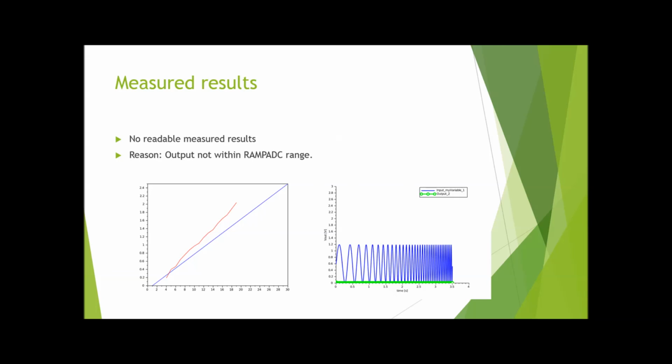I still want to talk about the error of the model. The problem with the error of the model is when the circuit is saturated, which means it will move very close to the ground and very close to VDD. In this situation, we need to have more measured results and take them into consideration in future models.